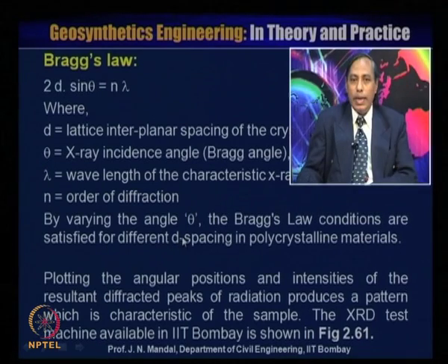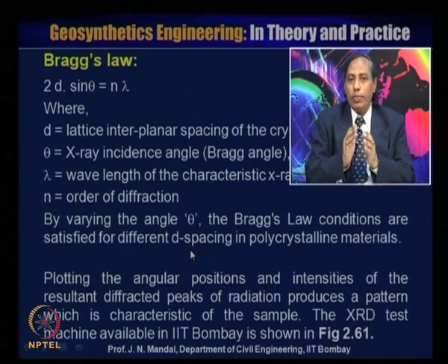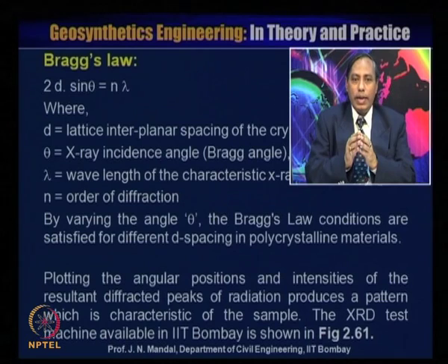By varying the angle, the Bragg's law conditions are satisfied for different d spacings in polycrystalline material. Plotting the angular position and intensities of the resultant diffracted peaks of radiation produces a pattern which is characteristic of the sample. The XRD test machine is available at IIT Bombay.